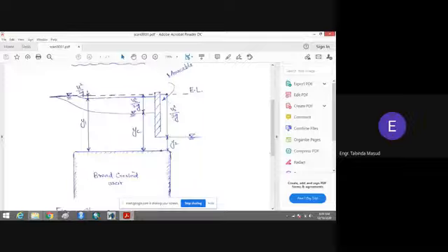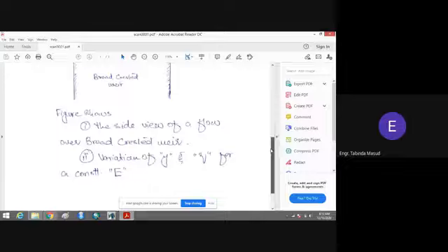But in all the cases, you can see that the energy line remains constant. This is what we discussed earlier, that we assume there is no friction, or friction is ignored, and we assume that the energy is conserved. That is, the energy line remains constant. Just before the gate, when the gate is opening, we have the critical depth of the flow and the critical velocity head.